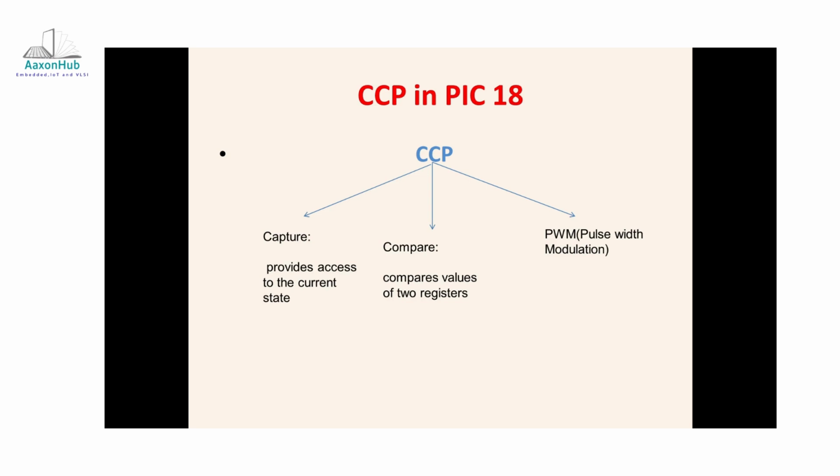More specifically, capture mode will simply provide access to the current state of a register which is constantly changing its value. In this case, usually Timer 1 registers are used. In that manner, it will capture the current instance of time with the help of timers. That is the capture mode of your CCP module.